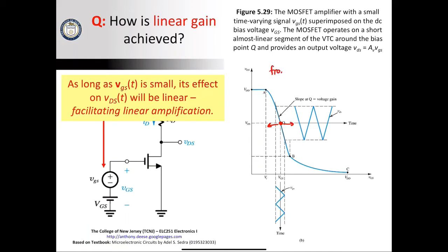Normally, the maximum swing is the lesser of the two values. Maximum symmetrical swing. It's sort of like if I'm standing up against the wall, how far can I symmetrically stretch out my arms? This far, right? Even though I have room on the left-hand side, because I'm constrained on the right-hand side, this is the maximum symmetrical swing that I can do. If I'm standing out here, then my maximum symmetrical swing grows. Obviously, if I end up on the other wall, then I'll get held on the other side.